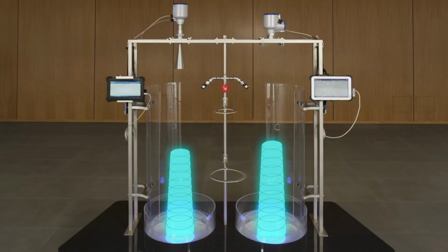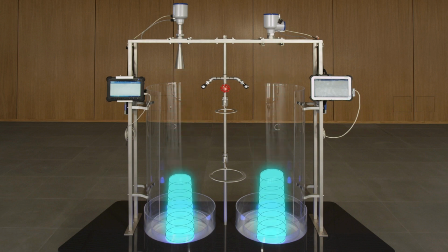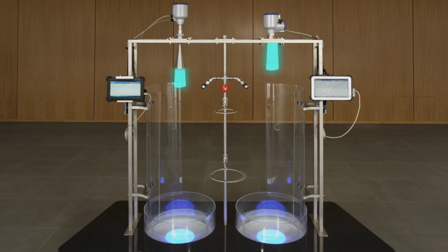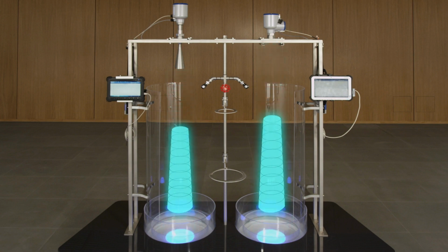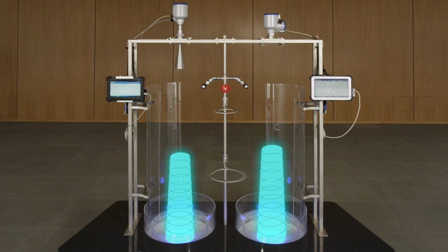The illuminated circles illustrate the areas detected by the respective radar system on the product surface. It should be noted that radar beams spread out conically from the antenna. For the selected system configuration, 24 GHz with an 80 mm horn antenna and 80 GHz with a 40 mm lens antenna, these areas are approximately identical.